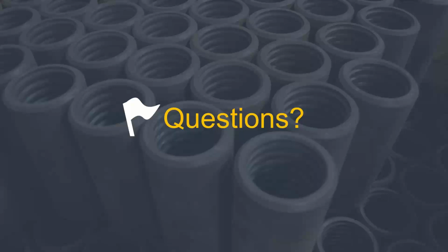If you've only got 2 piles in a cap and they're not tied together by a grade beam, you're always going to have that teeter-totter effect, even if you put them diagonally, because instead of teeter-tottering about the X or Y axis, you're just going to teeter-totter along the diagonal axis. So that's why the IBC says 3 piles or 2 with grade beams.